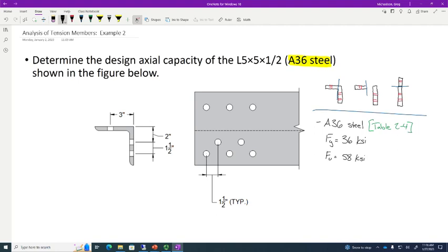A good example is if you're designing a steel structure out in California, and you've got really high load demands, really high seismicity demands. Maybe you need to bump up your grade of steel to be able to use a section that's reasonable for your project. But in most cases, you can go with an A992 grade.